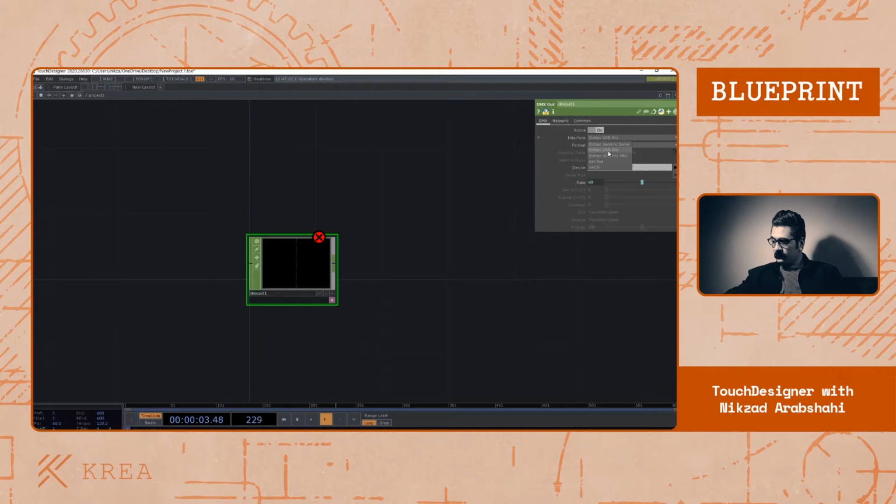Super handy when you want to send out channels over a local area network such as Ethernet, and especially when you're dealing with a massive number of channels or any situation that you want to send more than a single universe or more than 512 channels. And also ArtNet supports up to 32,700 something universes over one piece of Cat5 cable compared to a single universe over a DMX or XLR cable. Yeah, that's its advantage. Or you can use sACN if you want to, this one.